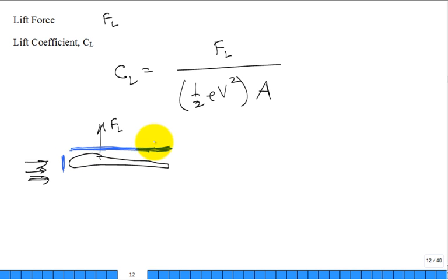And this is the planform area. This area, what do we call that? Silhouette area. So the area here is the planform area. It's looking down from the direction that the lift is occurring. It's that perpendicular area. So yes, C sub L, the lift coefficient, and C sub D, the drag coefficient, typically have different areas.